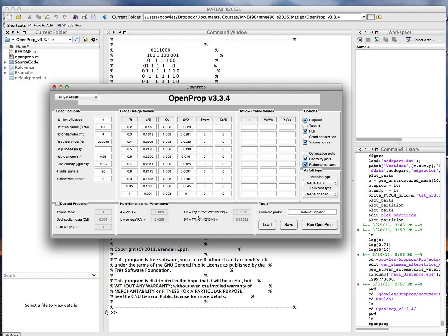Now, the true design capability of this code can take into account cavitation. Essentially, you put in lift coefficient restrictions on the blade, maybe as a function of radius from the hub, but you could just think in simple terms, a constant lift coefficient restriction, just like you did for your hydrofoil optimization problem, where you determined that the max CL, basically your CP min, gave you the max lift coefficient you could achieve before cavitation, and then you had to adjust the surface area of your hydrofoil in order to achieve the desired lift.